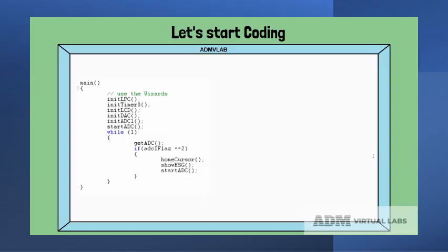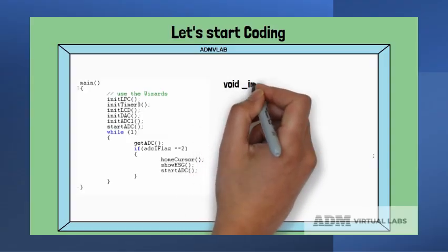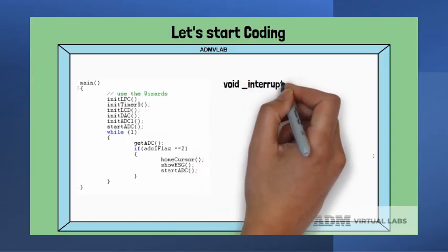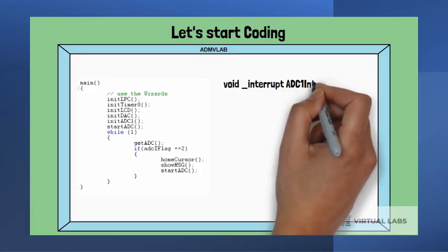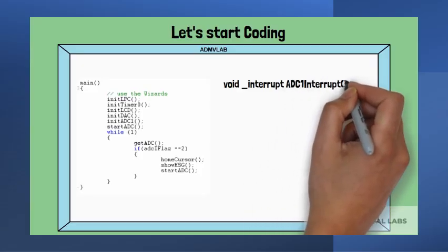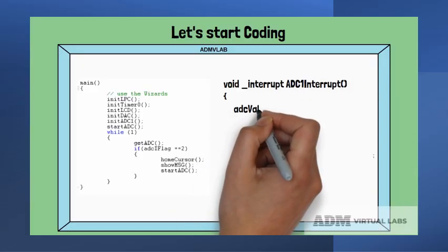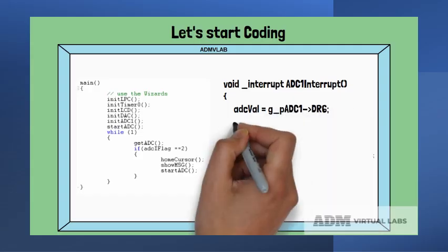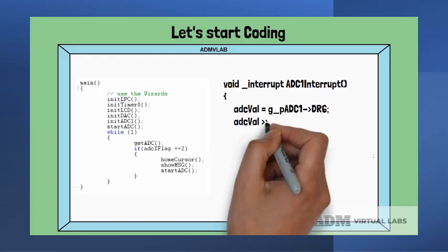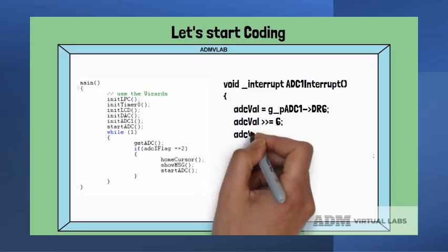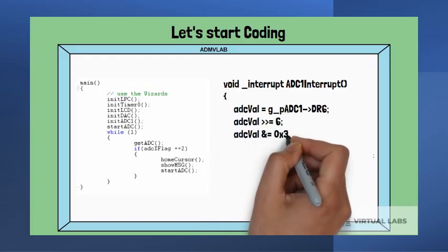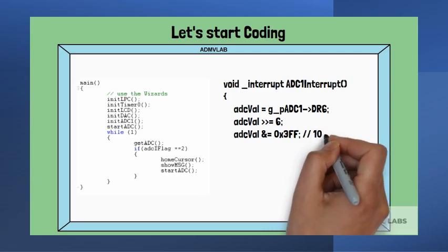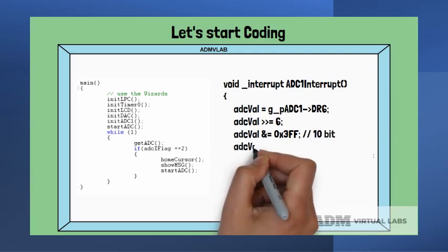The execution of ADC ISR indicates the ADC conversion is over. The ADC data is available in the ADC data register. As the ADC is 10 bits, the data is made available from bit number 6 through 15. We need to shift the data and compute external voltage value by defining the ADC voltage range and 1024-bit resolution.